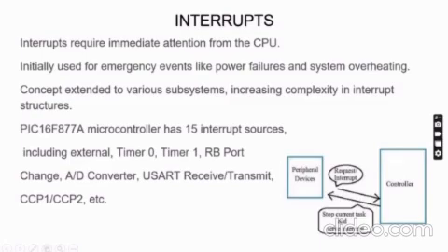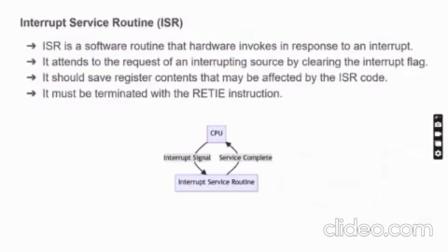Peripheral devices request an interrupt, it goes to the control and stops the current task. Whatever task it was doing, it will stop temporarily and serve the interrupt. After serving the interrupt, it comes back to the same position and continues the execution. This is the interrupt service routine.